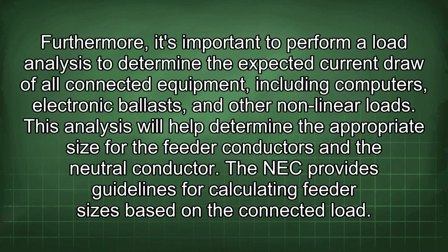Furthermore, it's important to perform a load analysis to determine the expected current draw of all connected equipment, including computers, electronic ballasts, and other nonlinear loads. This analysis will help determine the appropriate size for the feeder conductors and the neutral conductor. The NEC provides guidelines for calculating feeder sizes based on the connected load.